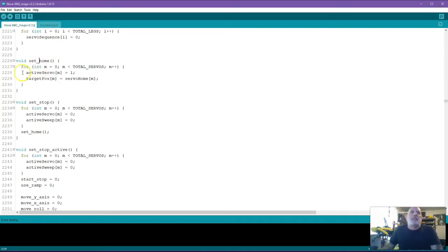Okay, so that's basically the bare essential you need to move a servo. So if you just want to test this, just go ahead and punch in your own little coordinate here. And you'll see throughout my code too, I do use the limits. So you could change this to limit, and then for minimum 0, for high 1, which will take it to its limit, right? And then often I'll say, well, let's go limit minus 50 pulses. So that's basically how I control and use that class. Those are the two absolute required variables that you would need to set, the active and target.